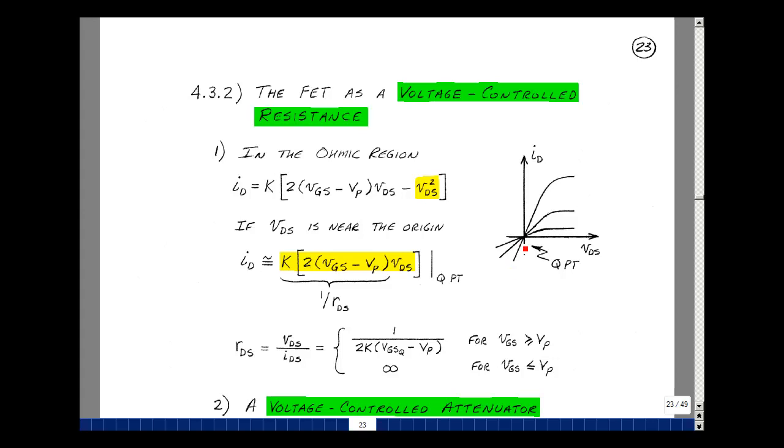and it's basically this straight line that begins to turn. We're plotting I sub d versus VDS, and here's I sub d and here's VDS. That's like an Ohm's law equation except for this term right here. In fact, this term is causing that little bit of turning, creating this parabolic effect. If we keep the drain source voltage small enough so that when it's squared, it's small compared to this quantity, then we could drop it out.